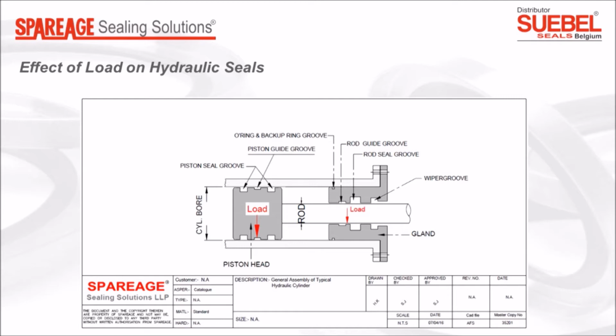Effect of load on hydraulic seals. Seals have only one function, of sealing. Seals are not designed and do not have the capacity to take the weight of the rod or piston head. Use of wear rings or bearing strips is strongly recommended to avoid the weight of the hardware from coming onto the seal, which results in excess interference on one side and less on the other, or damage due to crushing of the seal.